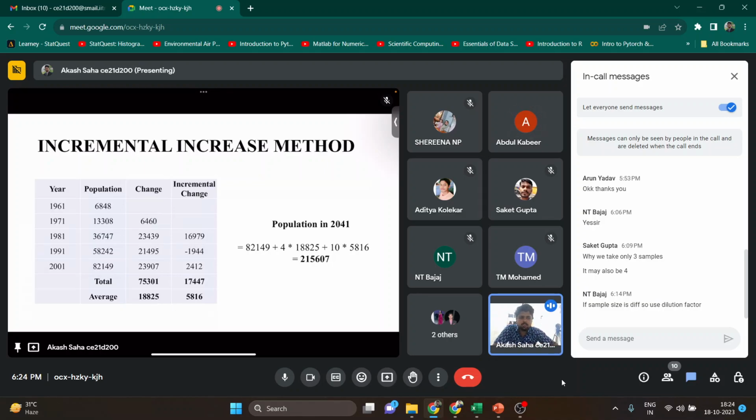So in population forecasting, we won't use the peak factor, but to design any particular element of our wastewater treatment plant or water treatment plant, to make it safer in the case of unforeseen circumstances, like too much flow coming, or suppose everyone is using water, at that time everything will come as wastewater. So the flow will suddenly increase. We cannot go with the average wastewater flow, right? So at that time, we have to use the peak factor and design it.